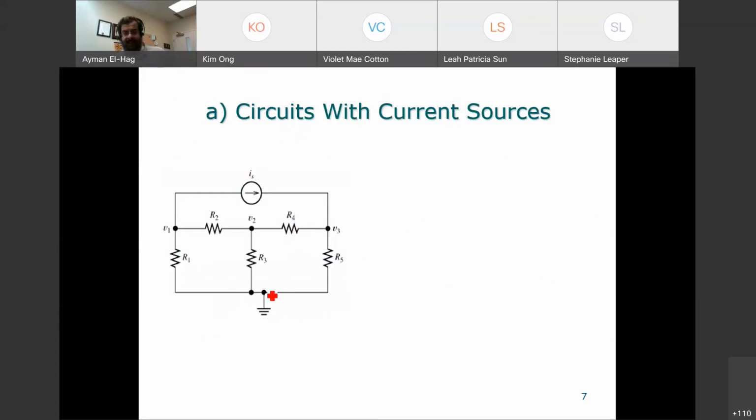One of the nodes is a ground, so this is given to us. Here V is equal to 0. So this is your ground, V equal to 0. And then we'll have 1, 2, 3 nodes. In total we have 4, so we need to assign voltages to 3 of them because for the fourth one we already know the voltage. So we have V1, V2, and V3. How many unknowns do we have? 3 unknowns. How many equations do we need? 3 equations. So now we need to assume the current directions.